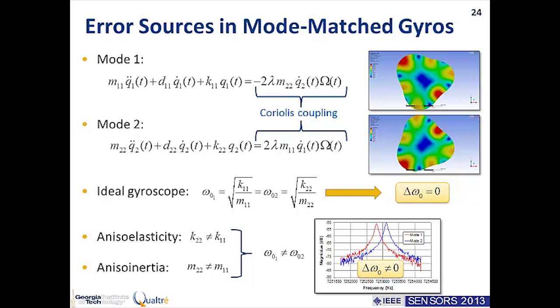And then, yes? How do you find the effective mass? So basically, when you have bulk-acoustic modes, there's only a certain portion of your regular mass, the mass defined by the volume of the device times the density. There's only a certain part of that that really contributes to the mode shape. So that effective mass is actually calculated from the equations that you use to calculate the resonance modes of the structure.